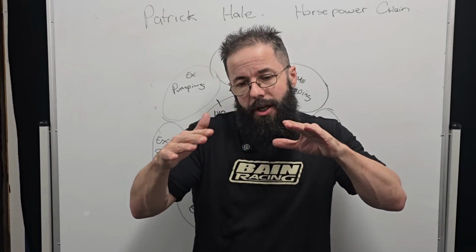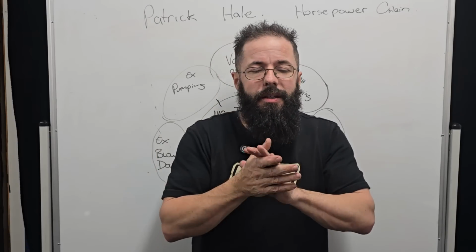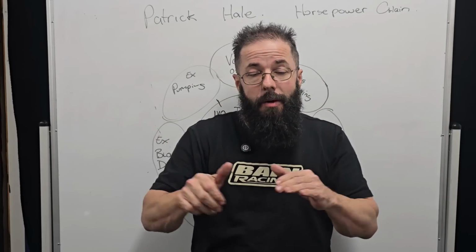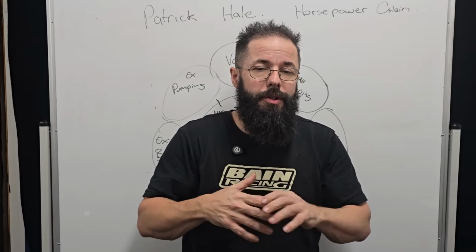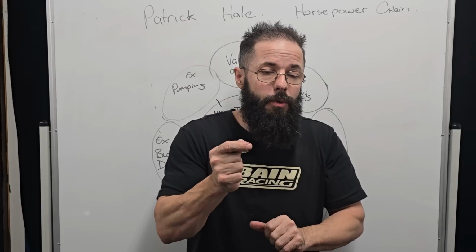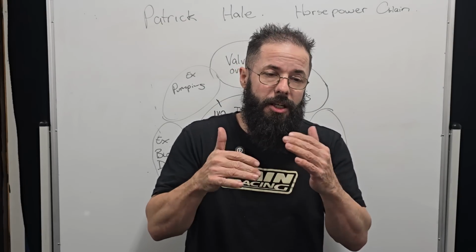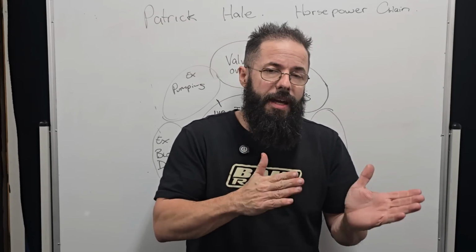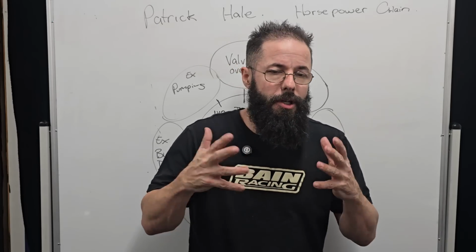They have a really nice chamber. There's no dead areas. They fan out off the top of the valve angle. Absolutely beautiful. So their exchange rates are much faster. They're smaller combustion chambers, which means we don't need as much ignition timing advance, which means we make more horsepower and so on and so on.